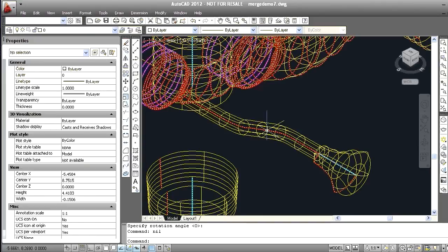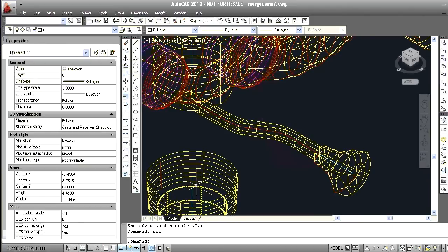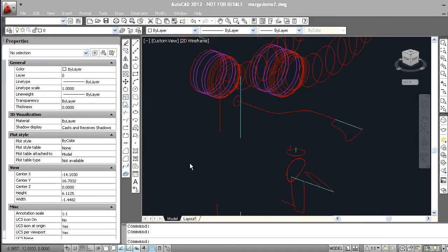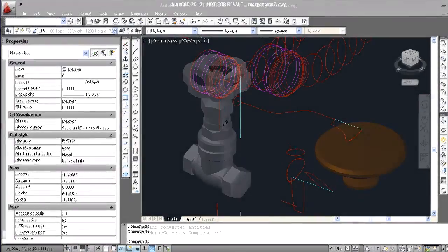This sweep here, you can see its sweep path, and at one of the ends is in fact the sweep profile. Another revolution here, again you see its axes and you see the revolution profiles. For lofts, you get all the ribs, essentially. The profile parameters all reside in a single block definition. It's easy to edit, analyze via program, also easy to purge when you're done.